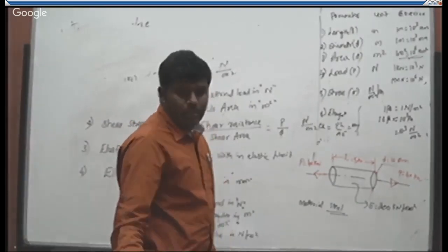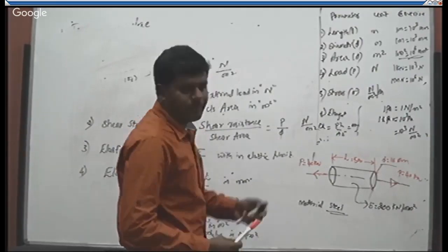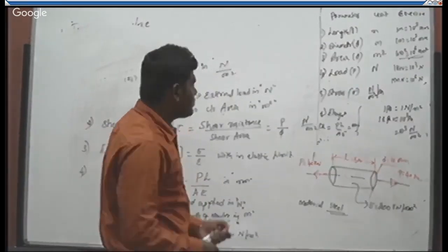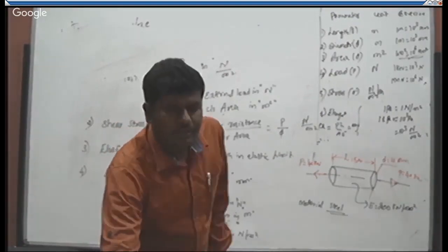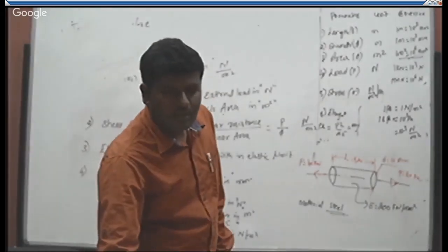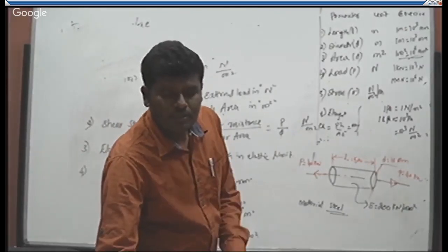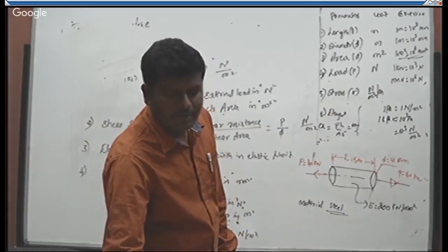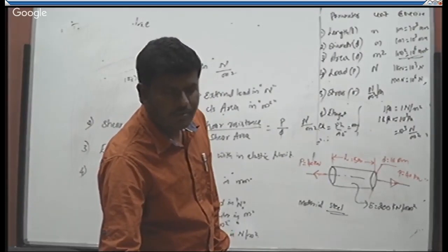Okay, let's find out the most suitable formula for finding the stress, strain and elongation. We have the load of 40 kilonewton. We'll convert that into newtons: 40 into 10 power 3 newton. And then Young's modulus they have given, 200 kilonewton per millimeter square, so converting from kilo, 200 into 10 power 3 newton per millimeter square.